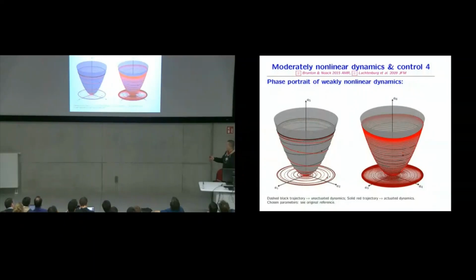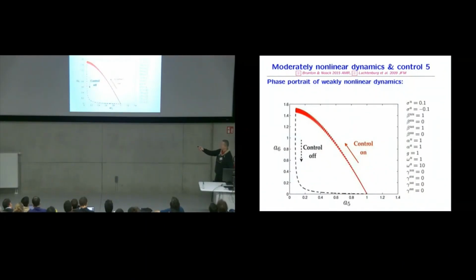Now, for the dynamical system, what we have here, without forcing, this is the first oscillator, A1, A2, A5. So you have the limit cycle here. On the second oscillator, you are at 0. Now, the transient from the steady solution here to the limit cycle: you start your actuation, you spiral backwards, and here you spiral outwards on the limit cycle, and this oscillator kills that oscillator. You can see it more directly if you look at the two shift modes. A5 is the amplitude associated with the first oscillator, and A6 is the amplitude associated with the unstable oscillator.